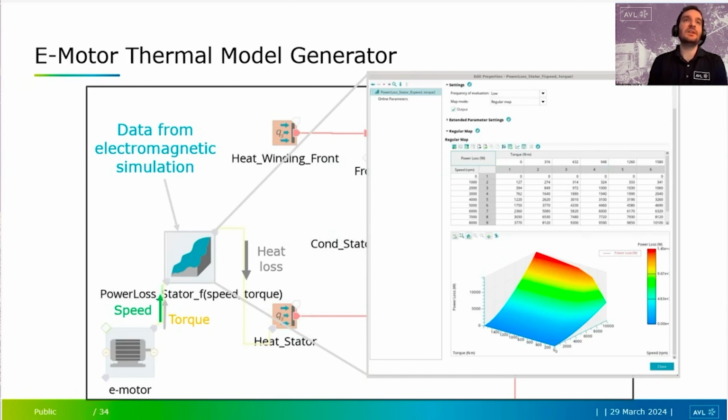And this is important because we're going to show a study here where you want to understand your thermal margin, because you run the risk of potentially demagnetizing your motor, or you just have an energy loss due to increased cooling requirements. So this would be something you get, and you'd use this in this way. You just connect it to your boundary condition here.